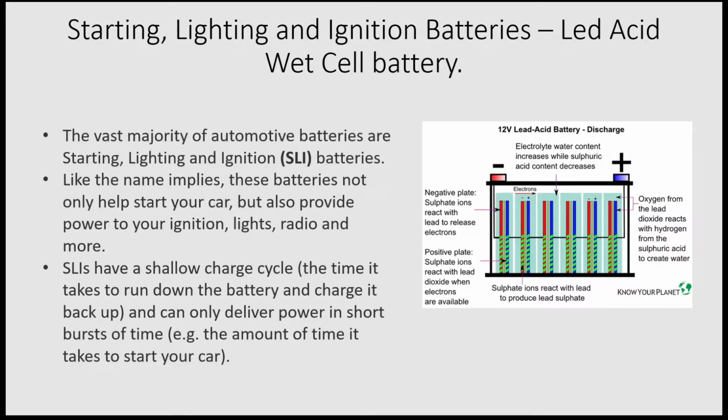Okay. All right. So the vast majority of automobile batteries are starting, lighting, and ignition SLI batteries. That means that they literally are there for the purpose of starting the vehicle, providing capability for the lights on the interior of the vehicle when you open the door, things like that. Okay. And providing power or energy for the ignition system on the vehicle. They are not designed to be saturated hard. They are not designed to be pulled down hard. They are not designed to run big, loud stereo systems on a consistent basis. They're designed solely to be put into the vehicle to run the everyday ins and outs of that vehicle, and not for long, extended amounts of time.